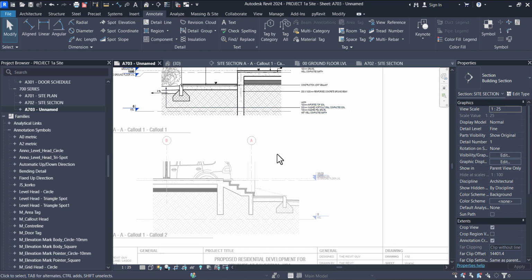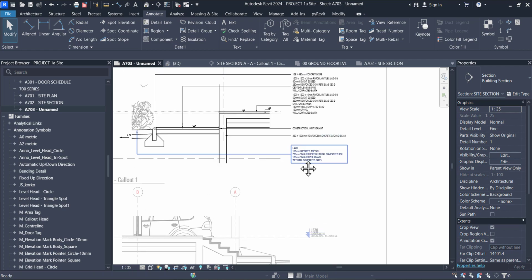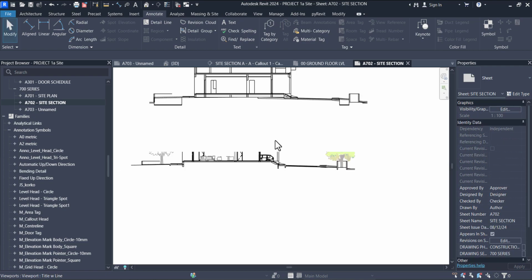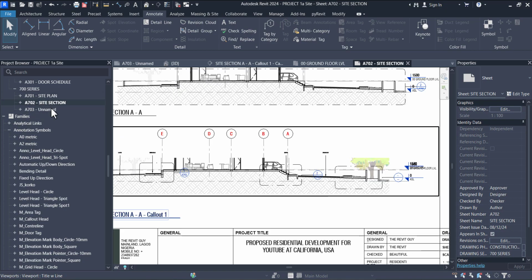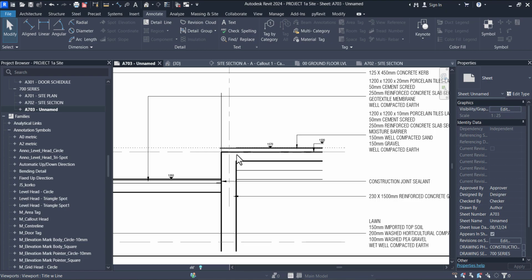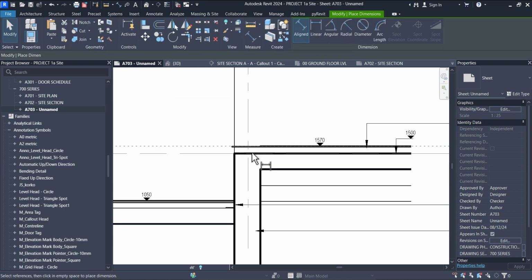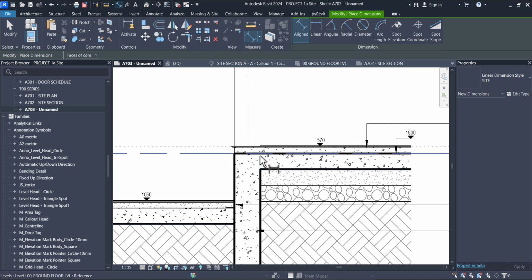So do the same thing for this. What I'll do in midweek, I will just detail this one and probably talk about it briefly. But this is like the fundamentals for site section. Like I said, you would get your site section. After that section, you do a blow up of the base, then you zoom into critical areas and you do the build up to the joint condition, give dimensions, mm, and joint condition and all this kind of stuff.